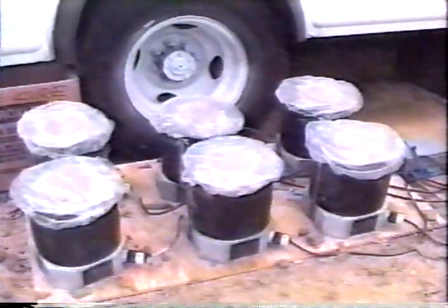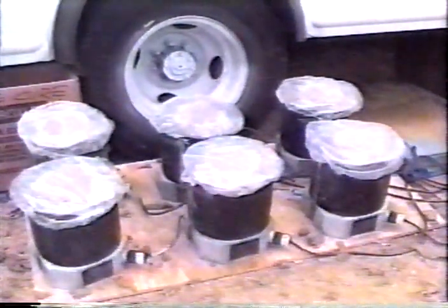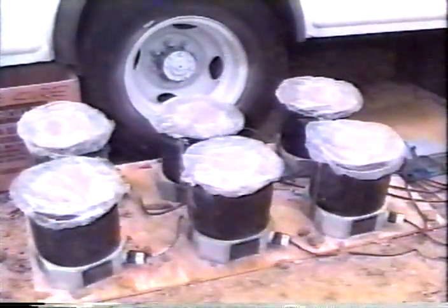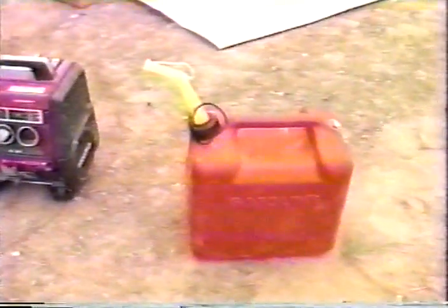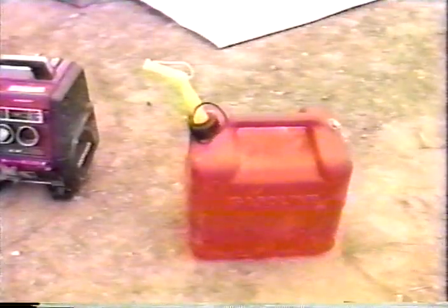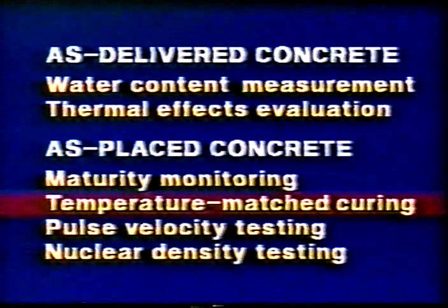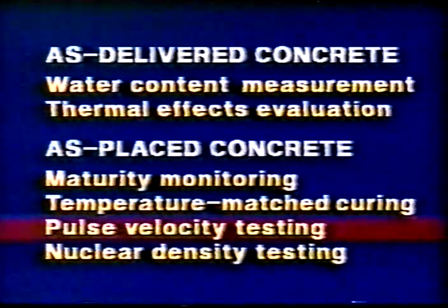One final note. There should be enough gasoline on hand to run the generator during the curing period. An extra container of fuel may be needed to refill the generator as necessary. That's the temperature-matched curing procedure. Next up is pulse velocity testing.